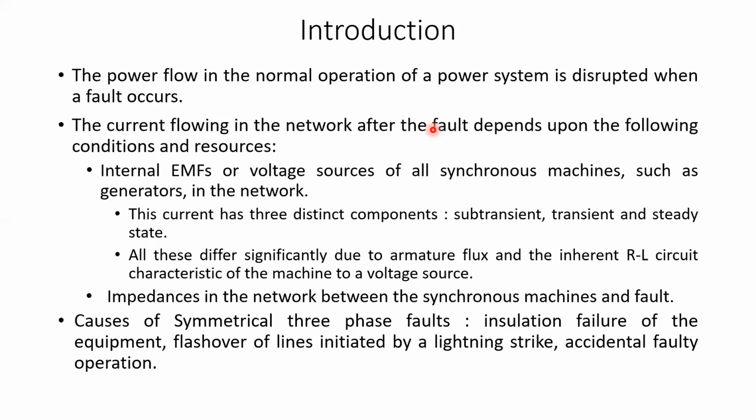Now, what are the causes of the symmetrical three-phase faults? The causes may be one of the following: insulation failure of the equipment, flashover of lines initiated by a lightning strike, or accidental faulty operation. We have studied what insulation failure consists of and the flashover of lines in Power System 1 in the 5th semester. So those are the major causes of symmetrical three-phase faults. Another cause is accidental faulty operation, which may occur due to natural or manual accidents.